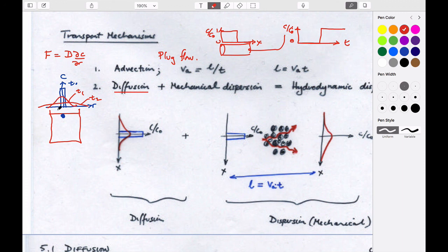And so if you think of this now in a porous medium, and you put this ink blob in the porous medium, then this initial distribution will move out, even if it's just sitting here in this porous medium. So you can think of it as a beaker, you can think of it as a porous medium, it doesn't really matter, it's the same behavior that's occurring. And so with the passage of time, Fick's law just means that this spreads out.